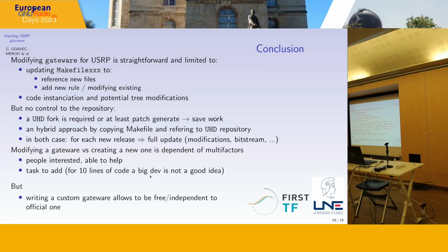Derek, maybe yesterday evening you had a comment about what not to do when changing the X310 gateware, just to make sure that everyone knows about it. Yeah, this is documented, but this is just a note about the X310 USRPs. There's a PCIe interface in there, and even if you're not using it, don't go in and remove the link to that to the FPGA. That's part of the requirement of the platform. And as the document will warn you, if you remove that and try loading it, then it'll actually brick the USRP. So that is a mandatory part of the FPGA design.